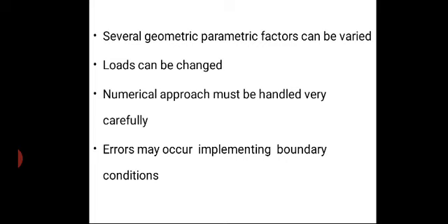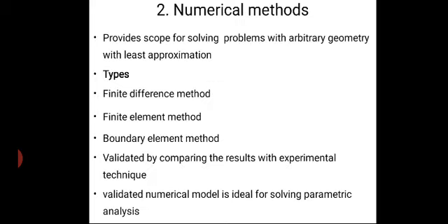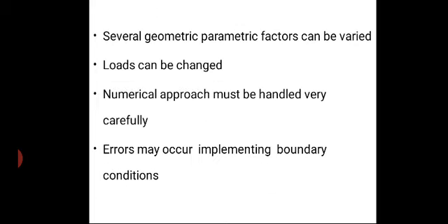Once we have validated it, several geometric parameters can be varied, such as loads can be changed. One problem with this is that the numerical approach must be handled very carefully, because it may give errors in the output values, which arise because of improper considerations or constraints in the body and improper locating of the nodes or key points.